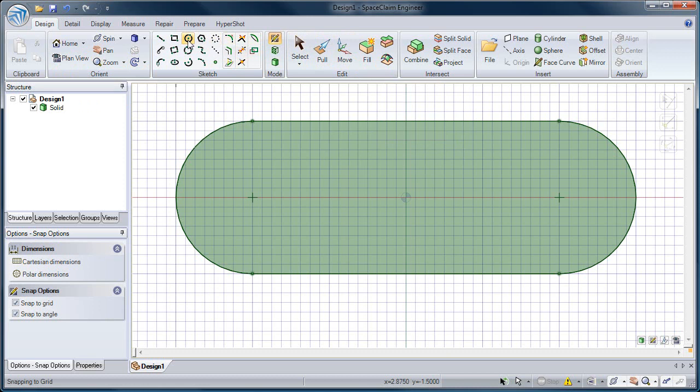But now let's start sketching. And I'm going to create a circle. And I'm going to snap this so it's coaxial with our circle here. And you can do that just by getting close to the center, and you'll see there's a green dot that appears on screen. And by clicking that, you can now create a circle. And you can type in any dimension you like. I'll type in 3/4.